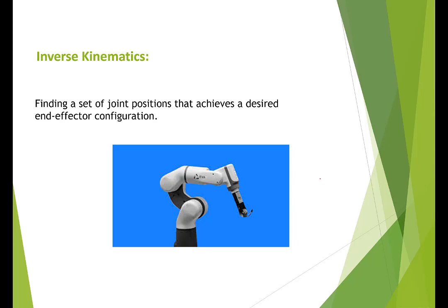And the next thing we're going to talk about is inverse kinematics. We said forward kinematics is finding the position of the end effector as a function of movements of the robot's joints. The joints can rotate or translate. Inverse kinematics is the exact opposite problem, which is actually more interesting: to know the joint movements as a function of the robot end effector position and sometimes even orientation.